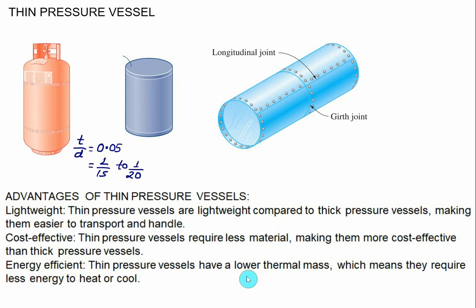So thin pressure vessels are widely used in various industries due to their advantages of being lightweight, cost effective and energy efficient. Their design is based on the theory of elasticity, and the material used should have high yield strength to sustain the pressure without deformation or rupture.